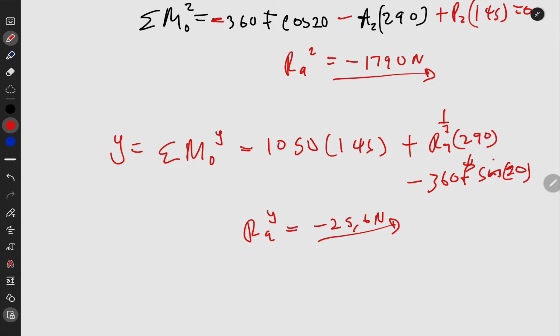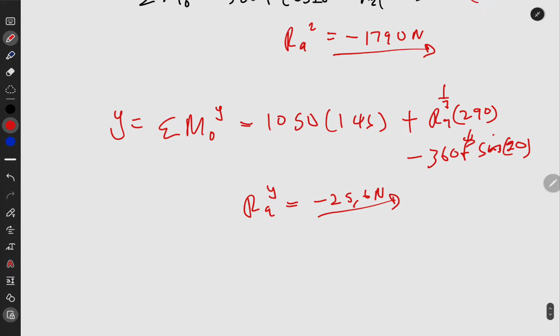So we now have all the forces. You could continue and do the sum of all the forces along Y, sum of forces along Z. You could now try to find what are the reactions on the other side, O, because we're focused on A, but A is sufficient enough for teaching purposes. Okay, so after that we can now substitute into our formulas, and then try to decide on which bearing we are going to use exactly.